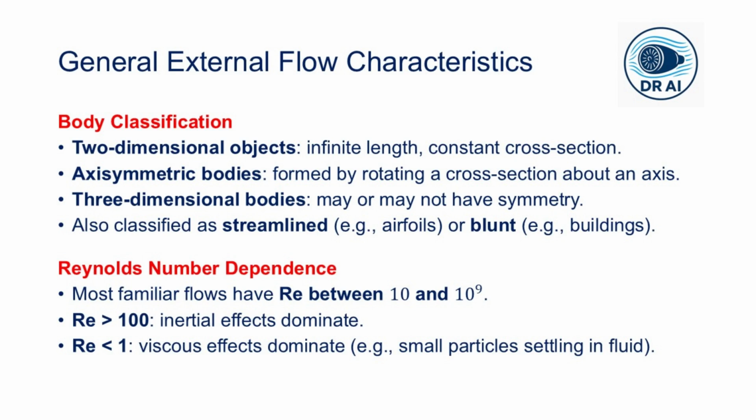So in fluid flow, the fluid particles in the boundary layer experience the same pressure distribution as those outside. They have to climb the pressure hill on the rear of the cylinder, but because of the viscous losses, they don't have enough energy to make it all the way. They stop. The flow separates, and we get the reversal flow. This separation dramatically alters the whole pressure distribution.